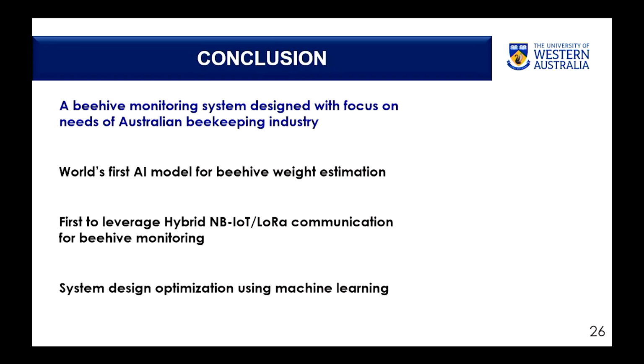Actually, okay, so you know the LoRa bands, header, and we are not using LoRaWAN. We are using raw LoRa. Simple raw LoRa transmission, not LoRaWAN at all, because we do not have a LoRaWAN gateway. We don't have to have those complexities. That's it. Simple binary data comes in as a string, gets stored, and NB-IoT picks it up and transmits.